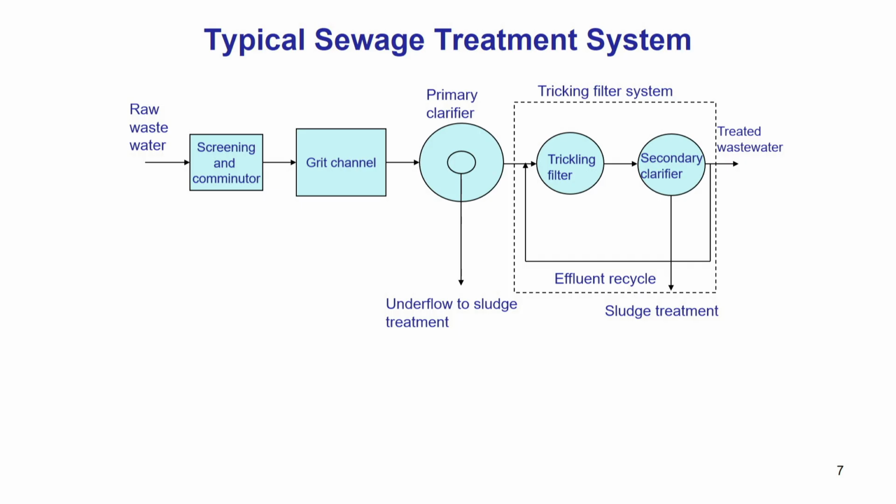And in this system, whatever sludge is generated has to be disposed of. No sludge recycling is done in this particular system, the trickling filter system. But here we can recycle already treated effluent if required.